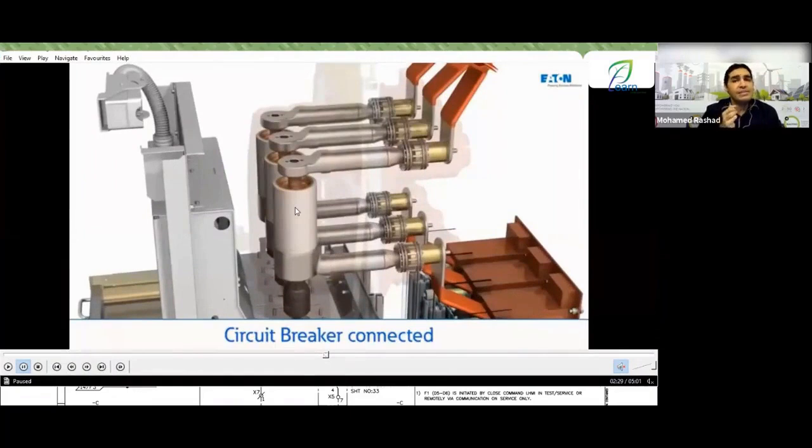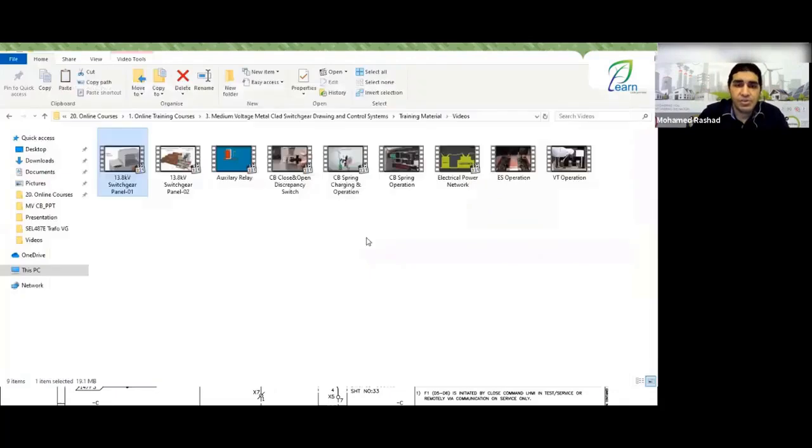Of course, this is the method used to classify circuit breakers. In the previous course on medium voltage circuit breakers, which you attended with us, there are 3 ways to classify circuit breakers: either by voltage level, whether it's low, medium, or high, or by the arc quenching medium, which is the medium for extinguishing the spark, such as air, air blast, oil, SF6, or vacuum, or by its mechanism, which could be a spring type, hydraulic type, or pneumatic type mechanism. Nice. So here I'm talking about the VCB, meaning this part where the poles of the breaker move to open and close. It moves in a vacuum, meaning it's something evacuated.